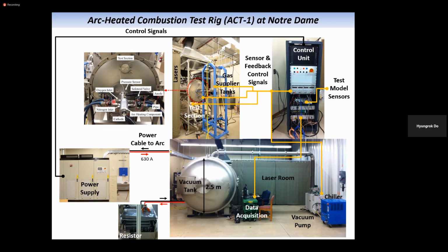So this system is working for about 1 second, and 1 second is long enough. If you want to operate it for a longer time, your arc should be extensively cooled, because the local temperature typically exceeds 10,000 Kelvin, and your system will start to melt down or evaporate. So, because of the short time period of the test, you should program the measurement execution time very carefully.